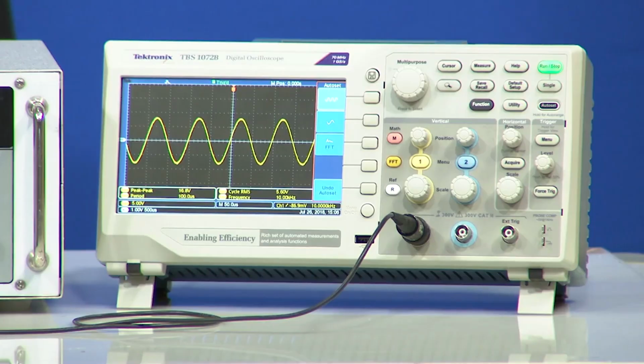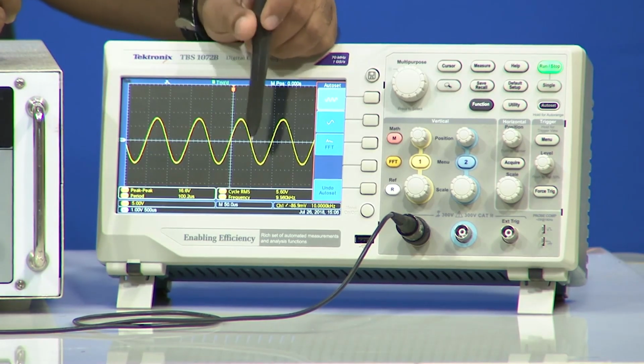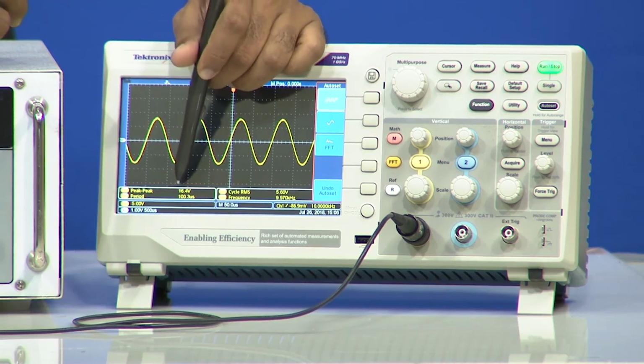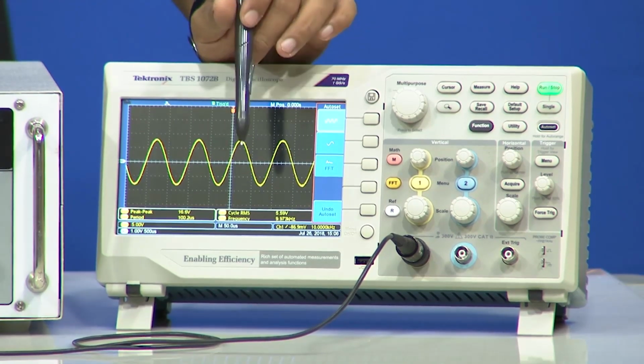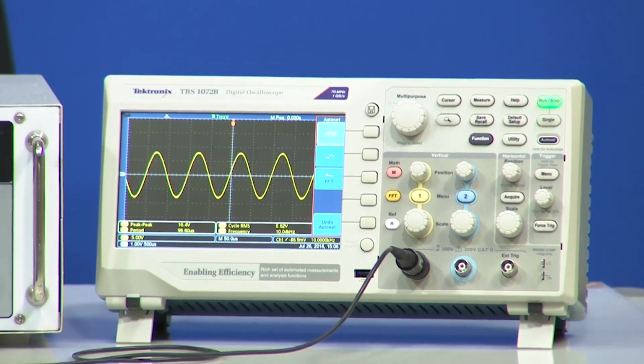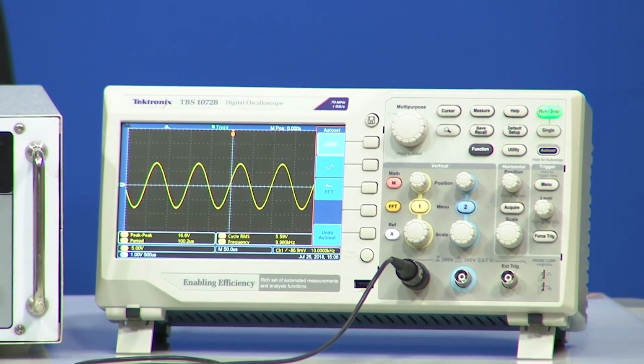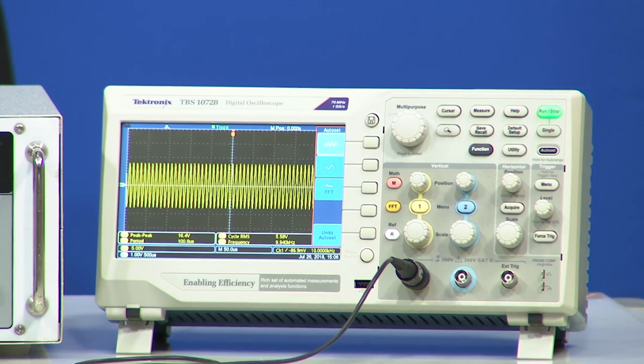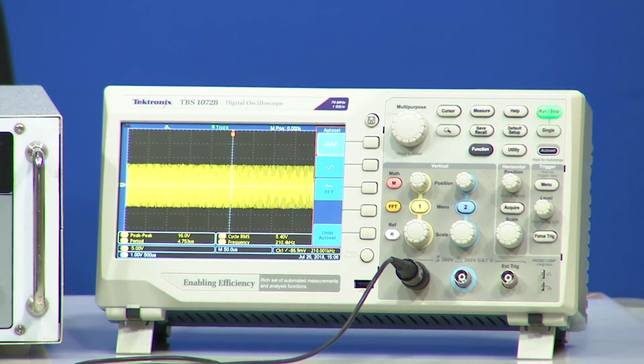Now we can see the oscilloscope. Our input frequency is 10 kilohertz, and we can see the output voltage. See here, it's around 16.4, so this is a faithful output as per our criterion. Now I am changing the frequency. Just constantly observe the output voltage. Now this is 110 kilohertz, and it is still 16.2 volt. Now it's 210 kilohertz, 310 kilohertz, 410 kilohertz, 510 kilohertz.